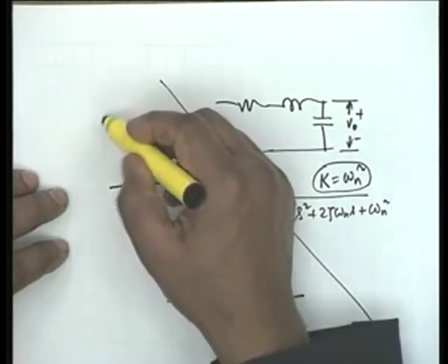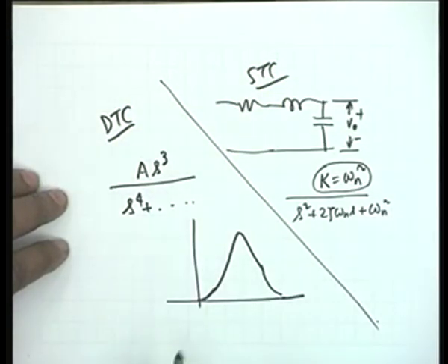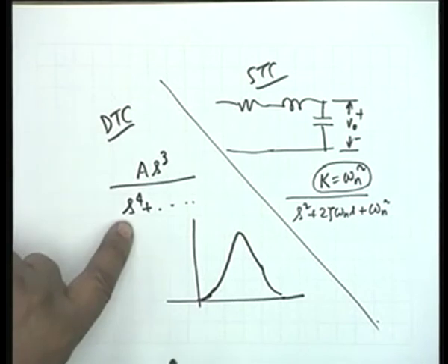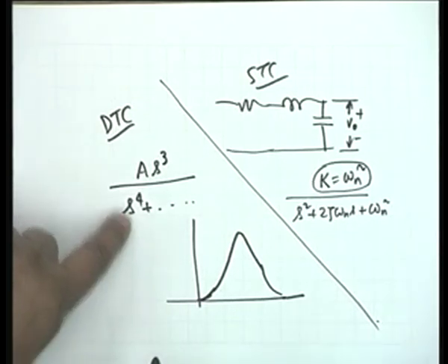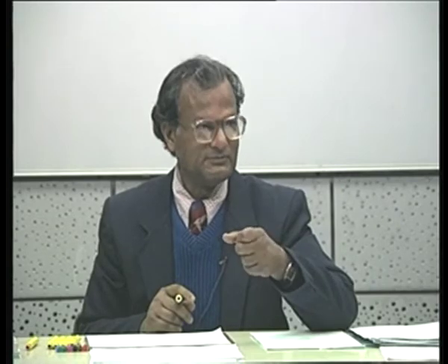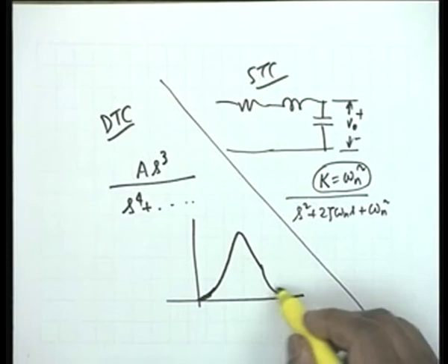The double tuned circuit DC response is 0. So, it starts from 0. At infinite frequency, when s goes to infinity, the highest power term in the denominator dominates. So, we get s cubed over s to the fourth. So, as s goes to infinity, the magnitude must go to 0. Alright. So, it starts from 0, it goes to 0.